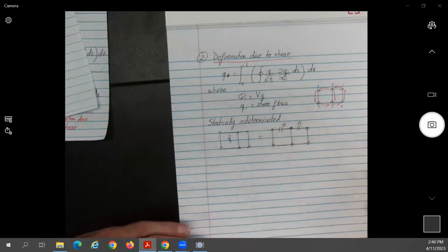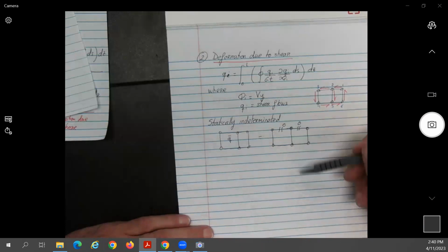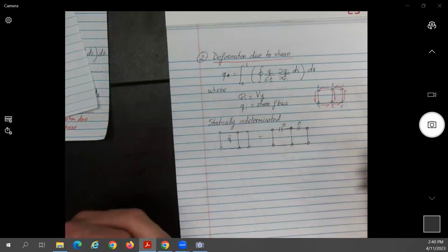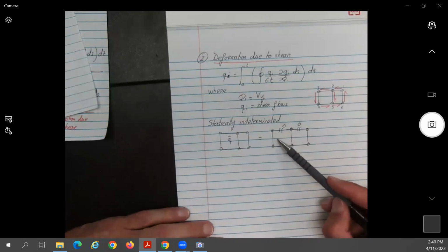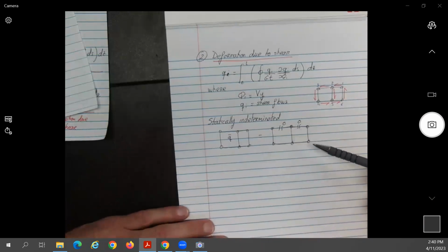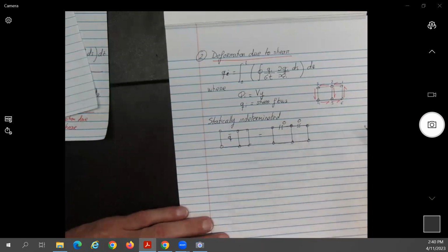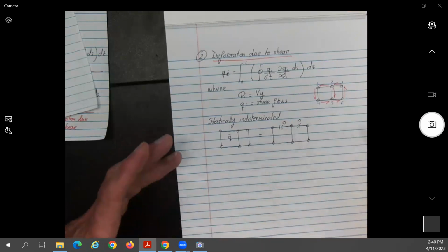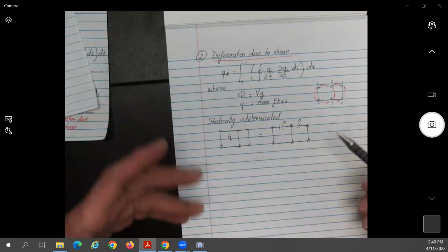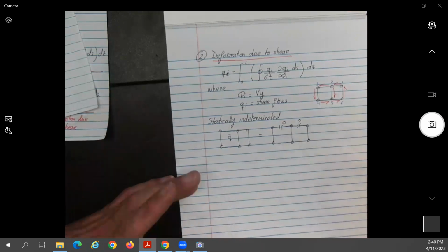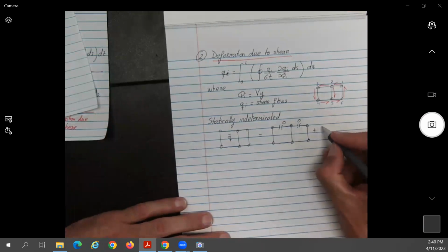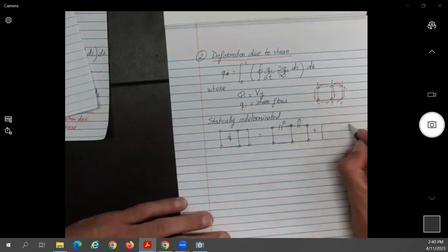2. You see over here, mathematically, you can do the cuts anywhere you want, but if the force is coming in the y direction, I like to do it on this one, because in theory, what should be the members that carry the loads in the vertical direction? Should also be the members in the vertical direction, no? Okay, so you can do the cut there, but I think you lose symmetry. You put it here, I think it's better. And then, what do you need to do for the second step?